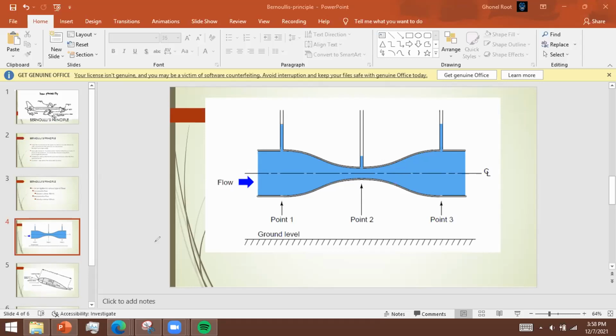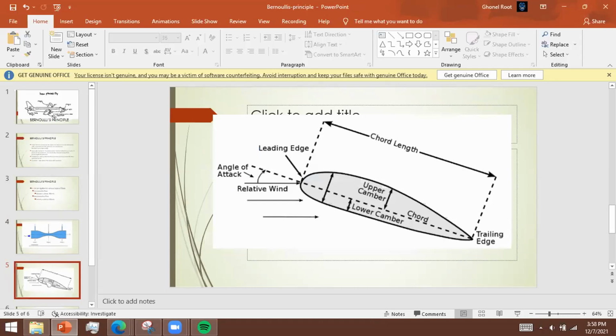Okay, and next, of course, is the wing, or the actual shape of our wing. I hope some of you know what the shape of the wing is called, which is what we call an airfoil. Okay? Airfoil. That's the name for the shape of the wing. You can see the shape of the wing in the side view of our wing, like this one. Okay? So because of Bernoulli's Principle, we come up with the best shape, depending on the type of aircraft. Technically, for jet aircraft, jet fighter planes, their airfoil is what we call a diamond.